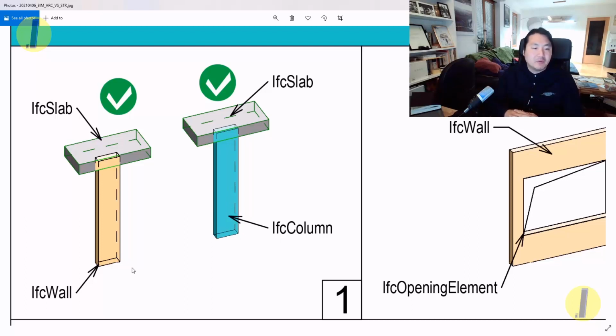Generally, when you divide this length by the thickness, and if the result is bigger than 4 units, then in that case you have to use wall elements. But this sort of regulation is defined by your national standard. But both ways are correct. You can build it as a column and you can model it as a wall. And also, again, in this case, the reinforcement will be no different.